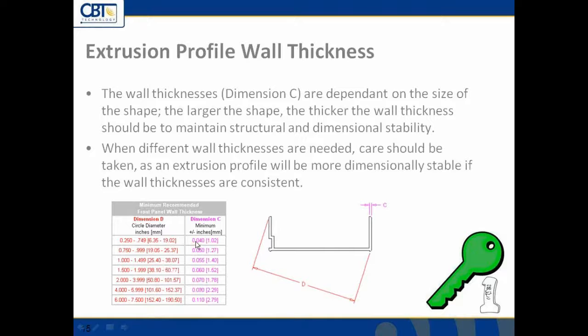So we can have some very small wall thicknesses, down around 1 millimeter or so if the part is smaller. But as the part grows in size, because of the extrusion process, it requires us to increase the wall thickness in order to get material flow through the extrusion die. So it's definitely a process constraint that we have here, which means if you want 50 thousandths walls across 6 inches, we're going to have a problem with that.